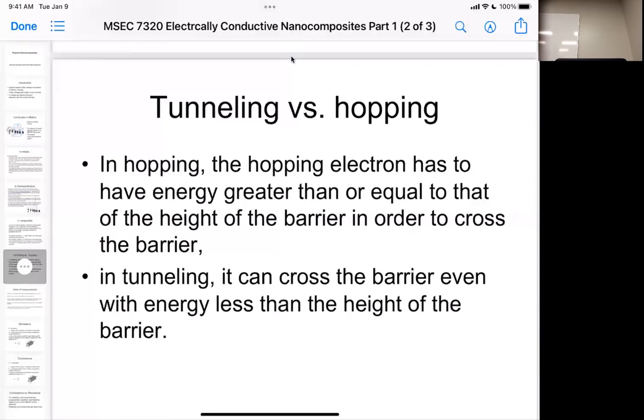But it doesn't mean that it's completely resistive in the off axis. It's not completely resistive. And the reason is we have hopping and we have tunneling of those electrons. As these electrons are moving through your dielectric material, there's two ways they can move. They can move by hopping, where I zip up this conductive material, get to the end, and need to find the next place to conduct. I still have a field drawing me to this side of the system, and then I can hop to the next system if I have enough energy to make that barrier.